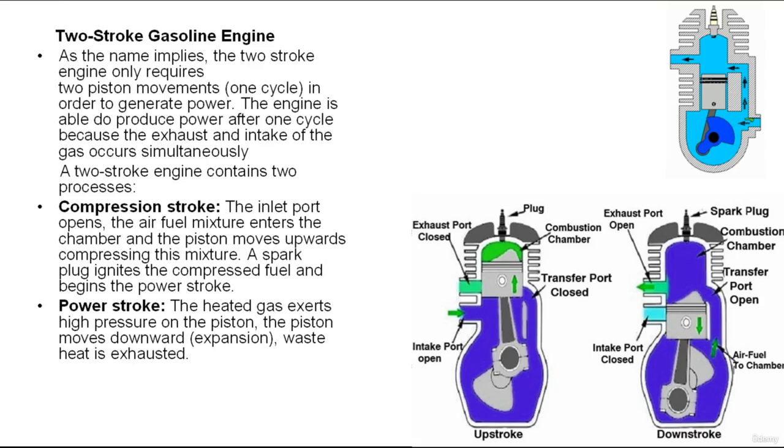We'll move right now to study the 2-stroke gasoline engine. In the past, several imported vehicles have used 2-stroke engines. As the name implies, this engine requires only 2 strokes of the piston to complete all 4 operations: intake, compression, power, and exhaust. This is accomplished as follows.